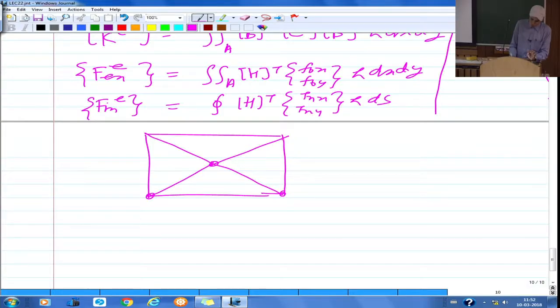Now you can number the nodes, global node numbering, say 1, 2, this has say 3, this is 4, this is 5. Element numbers you can say this is 1, this is 2, this is 3, this is 4. So you need to write the xy coordinates. The dimensions and other data are the same. So you try to solve this problem with discretization into 4 triangular elements. This is one, for heat transfer.